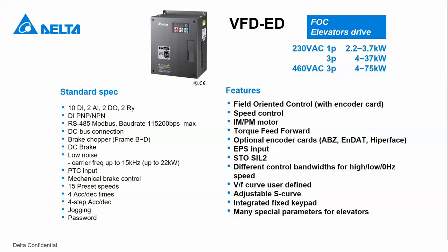So the drive can move the car to the closest floor in order for its passengers to be able to get out. It also supports typical encoders which you find in elevator applications, such as EnDat and HIPERFACE. And of course, some other typical functions like torque feed forward, which means that if you note a load on the motor, then when you release the mechanical brake, you can apply a torque feed forward in such a way that there will be a very smooth release.